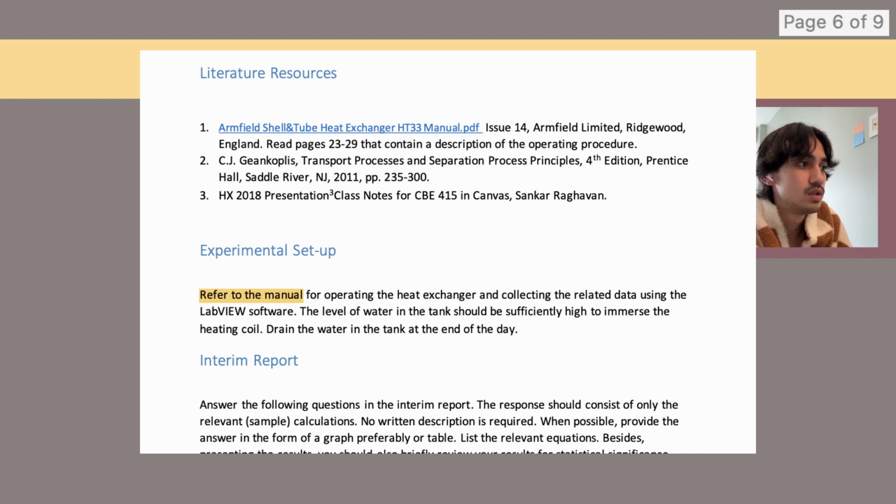Experimental setup. Refer to the manual for operating the heat exchanger and collecting the related data using the LabVIEW software. The level of water in the tank should be sufficiently high to immerse the heating coil. Drain the water in the tank at the end of the day.